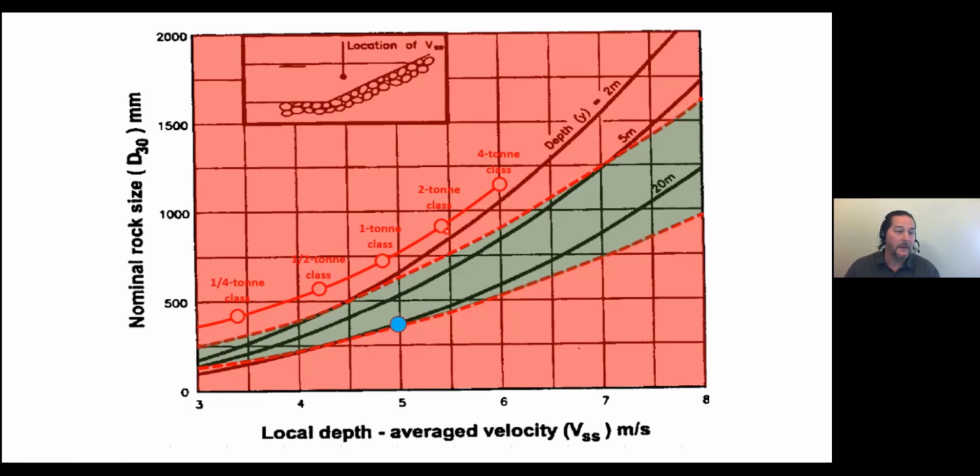Here is a 20-meter depth plotted at 5 meters per second. So that's an ISO line of 100. That was way off the charts. Here's one of 5 times 5, which is 25. And then here's one of 2 times 5, which is 10 meters squared per second, which is kind of getting onto the chart, but still dangerous. All of these could move things.